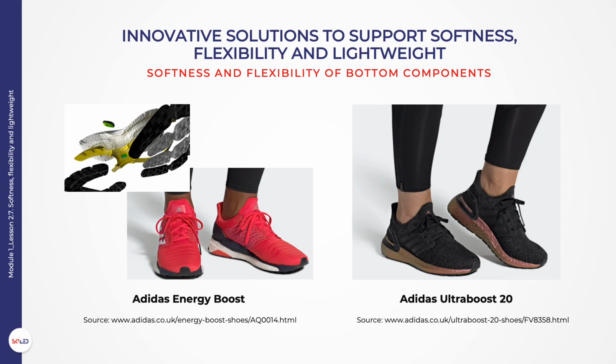As referred before, the bottom part of the footwear has the greatest influence on flexibility, with great benefits regarding the perceived comfort during walking and running. Softer materials will improve softness and flexibility while firmer materials will improve motion control. For example, duo-density soles often have softer materials on the lateral side to temper impact forces and decrease the velocity of pronation, and firmer material on the medial side to counter excessive pronation.